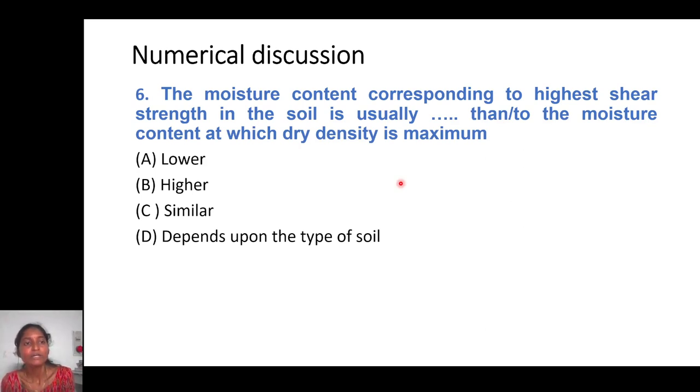In the field, this shear strength can change at any time. Let us say I have a vehicle of 10 tons moving on top, that is, let us say, normal stress. The amount of shear stress produced by the material will be different. If I keep changing the normal stresses, my shear stresses would keep changing. And if you take the dry density, we will be taking the worst condition, let us say soaked severe, and we assume that there will not be any further worse condition in the field. So we will be compacting all the layers to the optimum density.